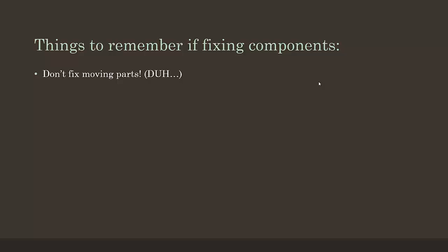So the main thing to remember if you're going to do this is that it is a methodology. Don't fix moving parts. You can have parts that still move around. I have them in that big assembly there. You do spend more time updating the assembly. I'm not going to lie about it.